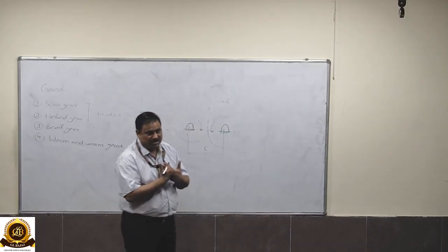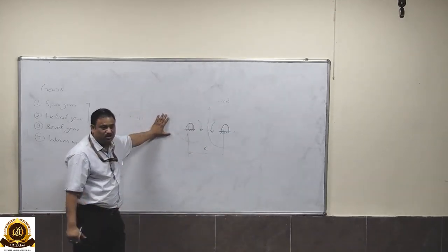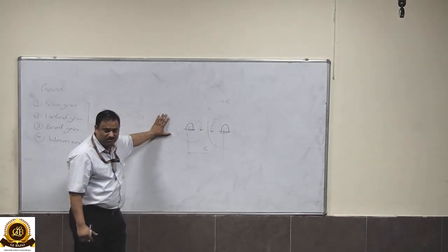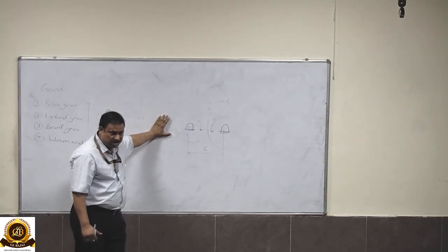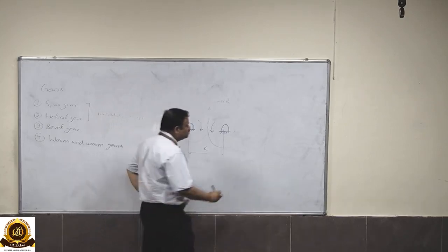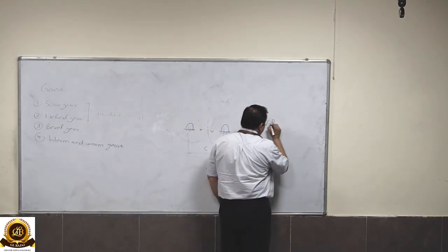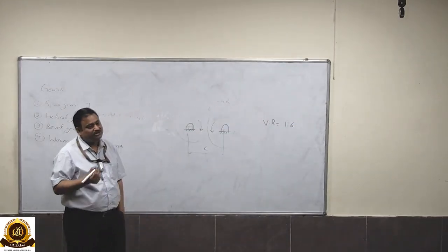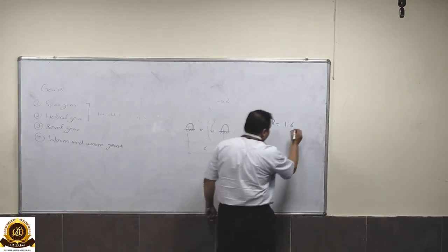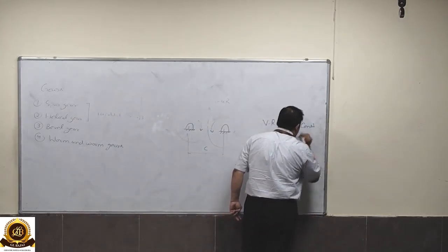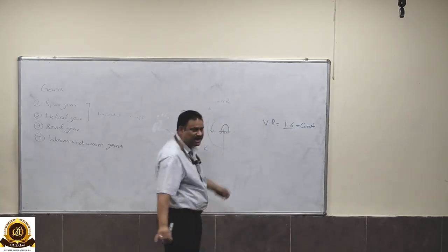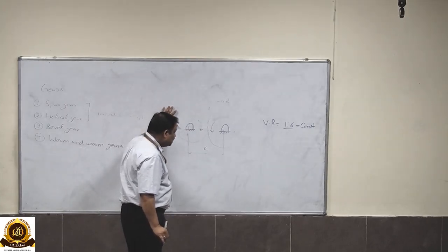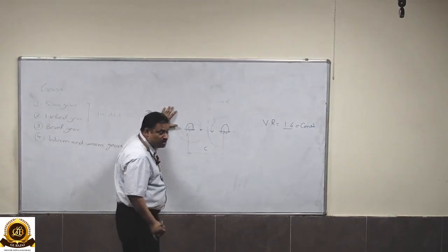In the case of gears, there is a fundamental law which is called the law of gearing. The law of gearing is basically for the achievement of the exact velocity ratio. Exact velocity ratio means, suppose the velocity ratio is say 1:6, then at any instant this ratio will be the same. It is constant. You can get the same velocity ratio at any time without any slip, just because of the toothed wheels.